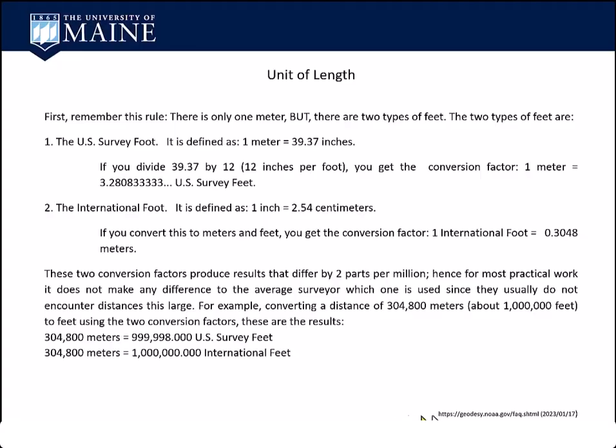And there's the link right here. If you go to this, there's a frequently asked question. This is just a copy of it. But with datum 23, you might have to go from US feet to meters and then to international feet, or if they're going to define it in some other way. Just be aware of that.